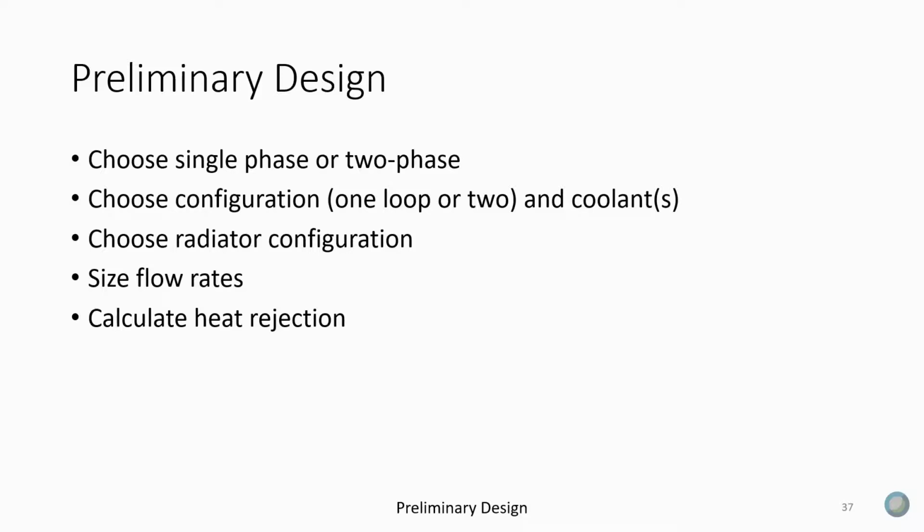So first choice, are we single phase or two phase? That's a good choice. Are we one loop or two? What are my coolants? What does my radiator look like? I see from Kayla we're scheduled until 11, so I can speak more slowly. So choose your radiator configuration, figure out what's going out there, size your flow rates.